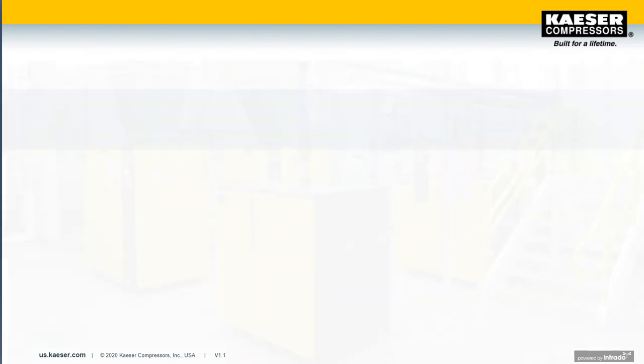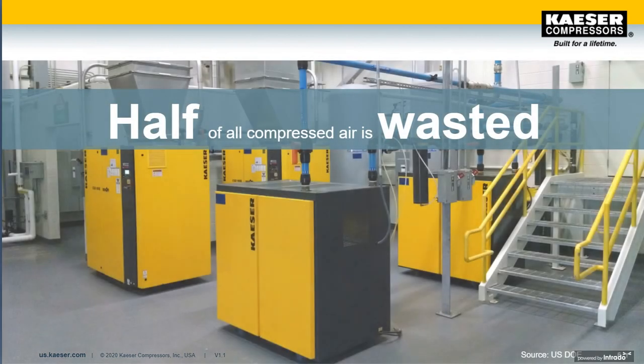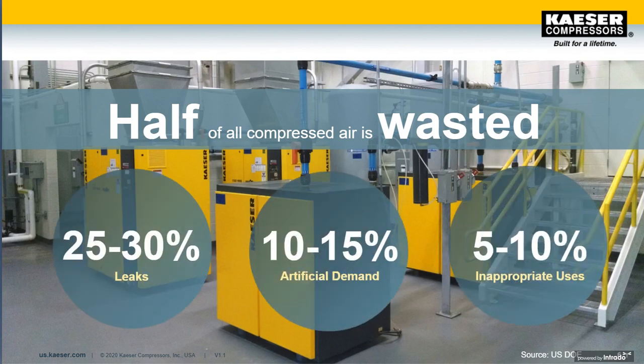Thanks, Werner. Any plant optimization should include what I'll call the big three. So we're talking about leaks, artificial demand, and inappropriate uses. Leaks, self-explanatory, but artificial demand, maybe not so much. This term we coined to express what happens in a compressed air system when operating pressure is higher than necessary. So all your tools are going to consume more compressed air, and likewise, your leaks are going to leak more. So whereas the demand is going to increase, it's not because the tools are requiring more air, it's just a function of increasing that operating pressure.